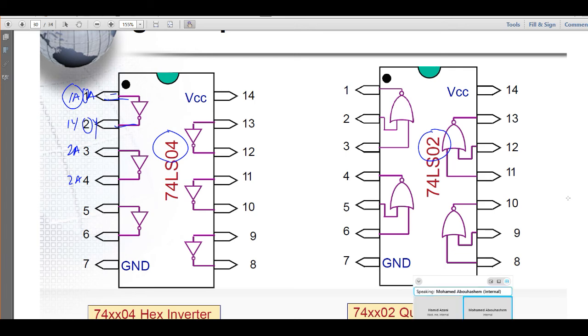Please, doctor. Yes. About the VCC, what does it represent exactly? Yeah, it's like your car. You have all options in your car. If you don't put gas in your car, you cannot start it. You cannot run with that car. Same thing here. All chips, you have to feed them. It depends on the chip and the data sheet, but most of the time it's between 5 and 15 volts, and you have to ground them. So most of the time pin 14 and pin 7 represent VCC and ground. You have absolutely to feed them before you can use them, for all chips.